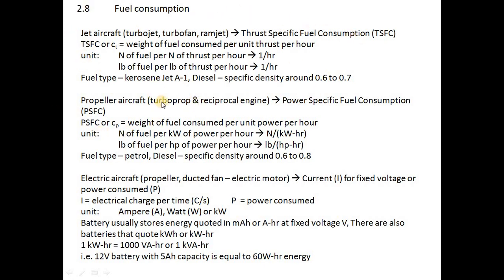For propeller aircraft, either turboprop or reciprocal engine, since the fuel is rated at horsepower or kilowatt, in other words, power, we're going to use PSFC or power specific fuel consumption. PSFC, or some they use CP. Some books they use CP.